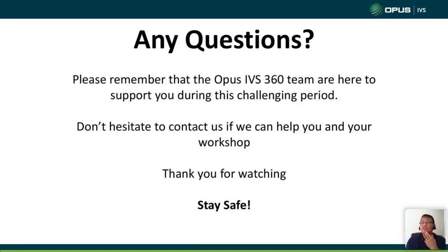And another question from Kit again. Would it be advisable to use a UV tracer dye to identify these oil leaks? I haven't tried one, but there are different types of leak testers, and I haven't tried the dye yet, to be honest. If you have a good adapter for the turbo, the best way really is to have a smoke test.